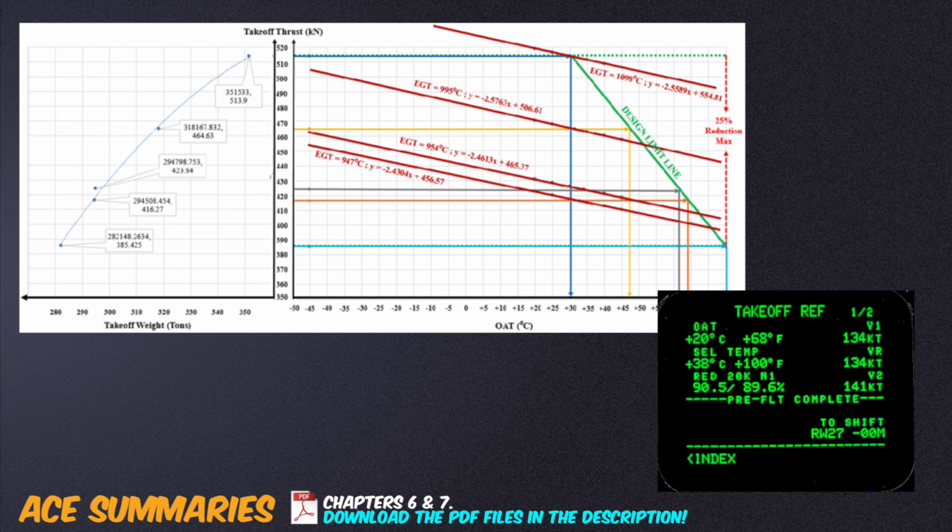When the flex thrust is selected during takeoff, the engine controller produces maximum thrust for the assumed temperature. If necessary, the crew can push the throttles into the takeoff go-around detent and request full power from the engines.